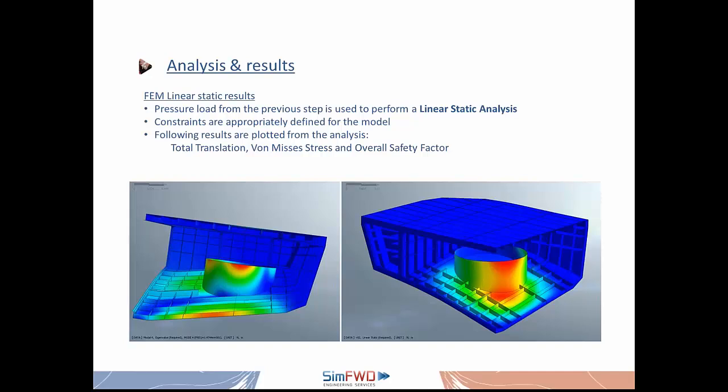As we've seen before, the structural model that we created with BVB CAFE Modeler, we meshed it, imported it into Midas NFX, and now it's ready for use within the Midas NFX platform. We have left all the constraints to be defined in Midas NFX, like boundary conditions and also, as you saw, the loading derived from the CFD analysis.